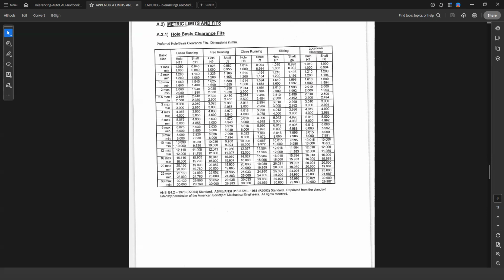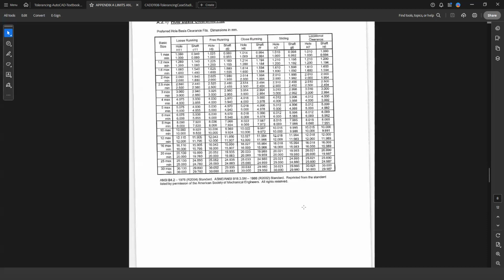And that's just, I mean, almost every mechanical part out there has a bearing associated with it or a shaft into a hole. So we just found that we weren't holding critical enough tolerances, and it was causing random breakage, which is the worst. It took them a while to pattern, like, why are we breaking here and here and here? It's like we built this stuff for 100 years. What's going on? Well, we're just getting sloppy with our tolerances and we weren't tolerancing things correctly.